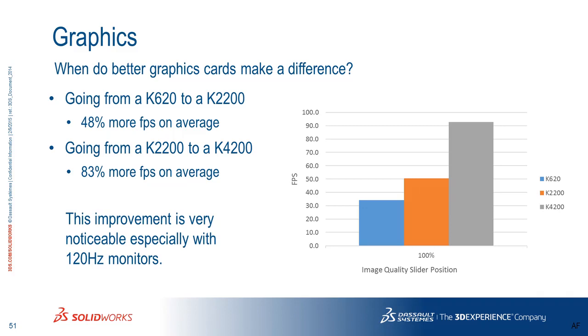That's on the graphic regeneration. When you build the feature, the 3D build, you still cannot do anything because it says regenerating graphics. It's a good question. He asked if we did any testing on the graphics regeneration portion of SolidWorks. We actually stripped that out this year and tested just calculative SolidWorks effort, and did the graphics just in the spinning actions. This was a question of the customers: is it worth investing in a much more expensive video card in order to reduce that time? No. Yeah, it is not worth the investment for that reason. No, sir.